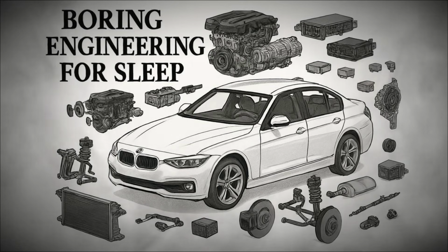There are also more advanced designs, such as multi-plate clutches, used in motorcycles or high-performance cars, where multiple discs provide greater surface area for handling more power in a compact space. Automatic transmissions typically replace the manual clutch with a torque converter, which is a fluid coupling that transmits power smoothly without the need for a pedal. Dual clutch transmissions, however, still use clutches, but they are controlled automatically by electronics and hydraulics, allowing for extremely fast gear changes without driver input.